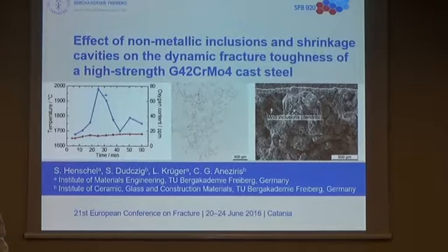Here you can see an aluminum oxide, and the manganese sulfide is mostly in a dendritic structure, which appears this way when the dendrite is of course cut in an arbitrary plane. And we can see also here that there is no angular dependency on the distribution of the non-metallic inclusions.